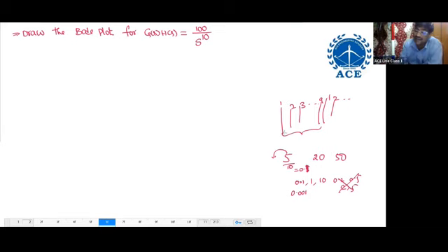Then only 1 decade will complete in 10 lines. Here 10 lines will be there, 1 to 1. So compulsorily 10 lines should be used for the decade calculation. For example, if I take for this group of frequencies multiplication factor 0.1, this is 0.1, 0.2, 0.3, 0.4, 0.5, 0.6, up to 0.9, then this will become 1. That means 0.1 to 1 is one decade. Again, the next group should be multiplied after 1 decade, means group multiplication factor 1. Again, the next group should be multiplied after 1 decade, means 10.